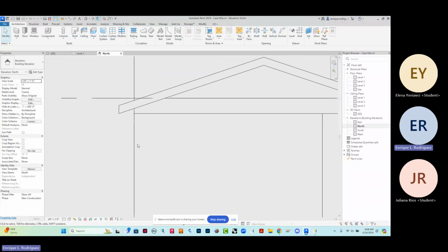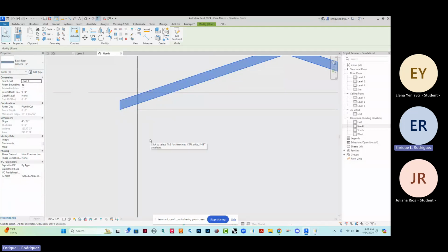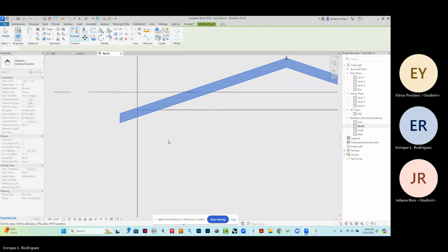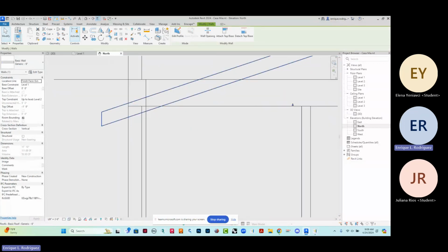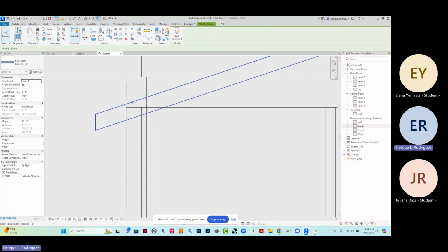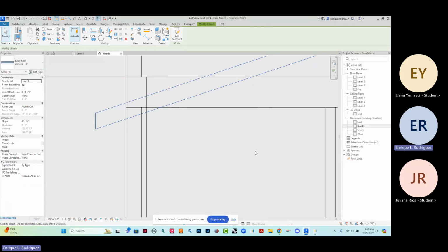Now, here's the big difference. When you picked a line, rather than a wall, notice that this outside point of your offset is the one that's set at 9 feet. Now, since we have to lower them anyways, we can just lower it right in here, and I can lower it down if I want to. Okay, but what I would do in that case, I would definitely go to wireframe so that I can visually start moving it up.